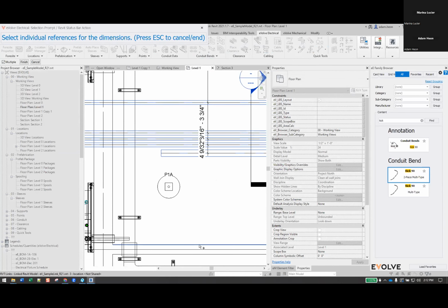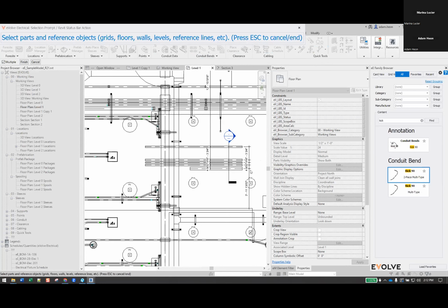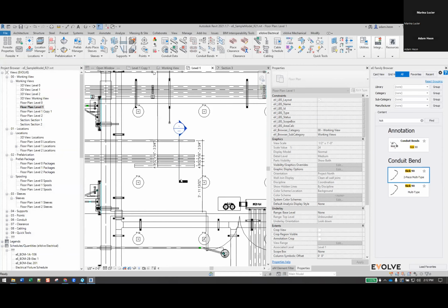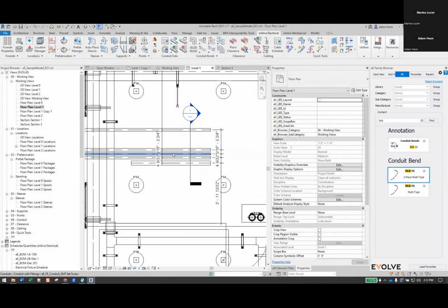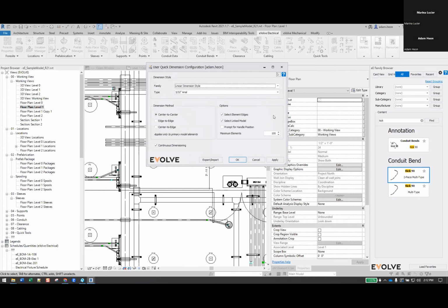Select my elements here, select something there. So as I zoom out, you'll see the dimensions onto the right. The command finished, and it didn't look visually like anything happened. So keep that in mind if that's unchecked, that depending on how zoomed in you are and what you're dimensioning, those dimension lines could shoot off screen and off your view.